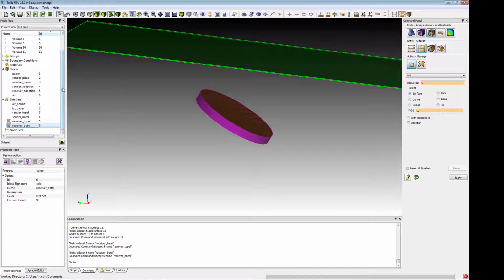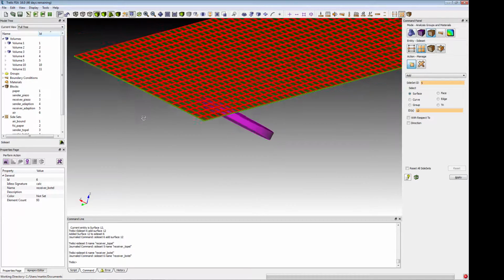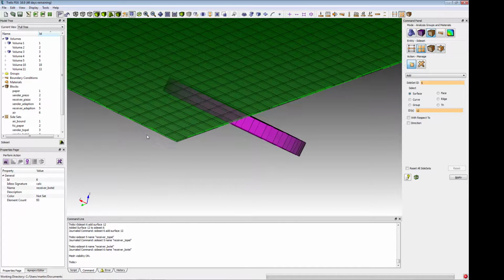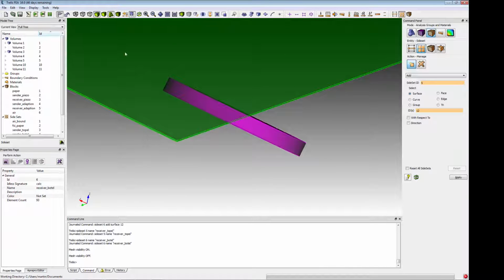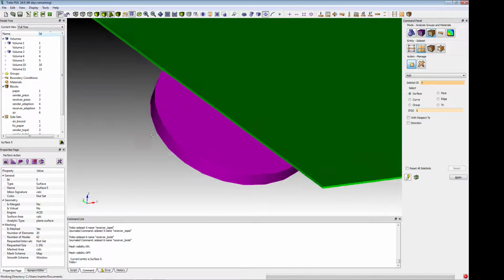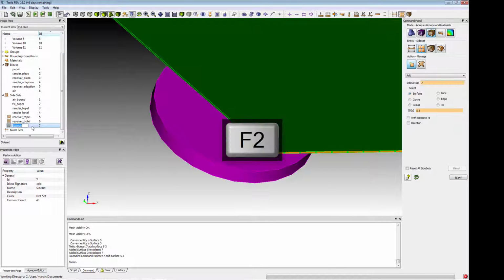Is there anything else still missing? Yes. On the bounds of the paper, mainly here. Let's do the solid model. I want to specify another side set using this face and also this face, and we will use those 2 faces as absorbing boundary conditions.